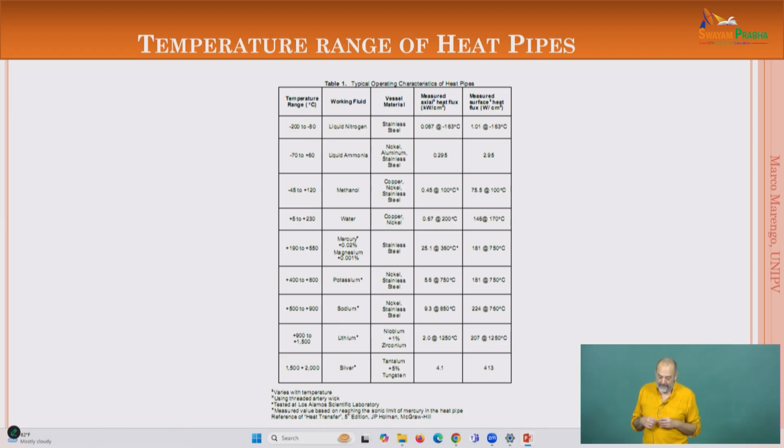And also maybe we can have even lithium heat pipes that are going up to 1,500 C or even higher. Myself, I use, for example, sodium in a thermosiphon with 1,000 degrees plus minus at the evaporator.